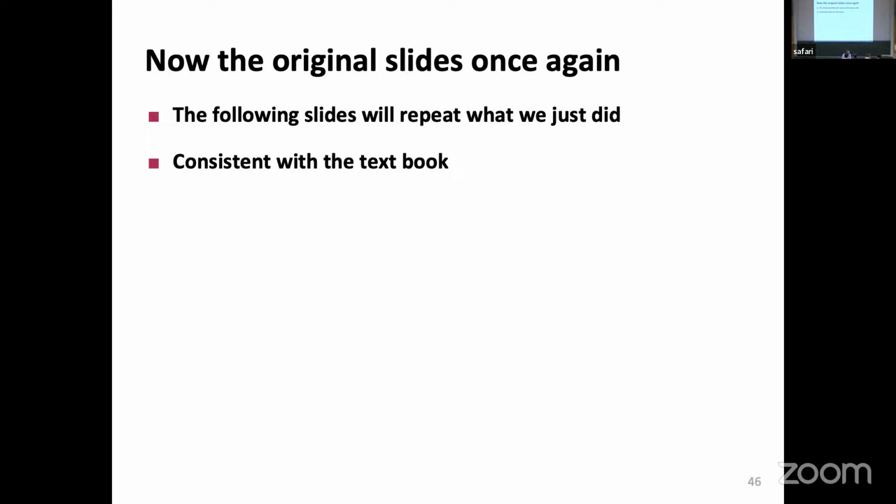I mean, hold time is always the problem. However, when you look at the type of things you are doing, we are more likely concerned with setup time because the paths are very long. Hold time is only an issue if there can be short paths. Maybe I can come up with a good example and ridiculously short path. The single cycle thing, it would be very hard to find. I mean, it would be difficult to find something that would violate the hold condition.